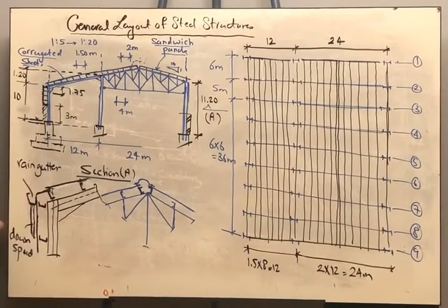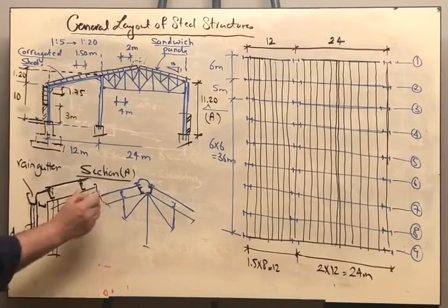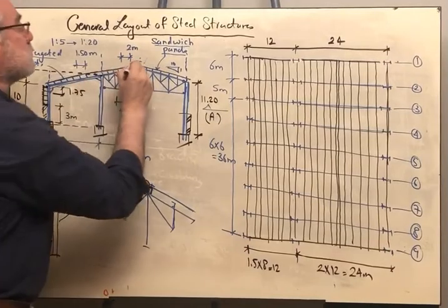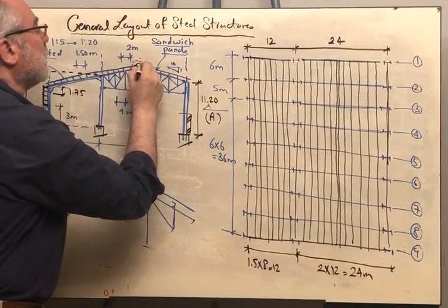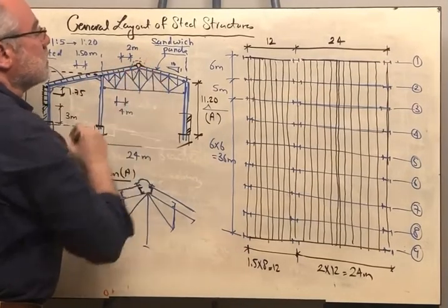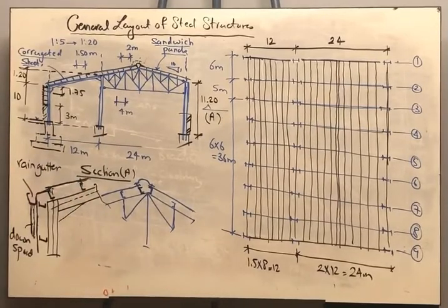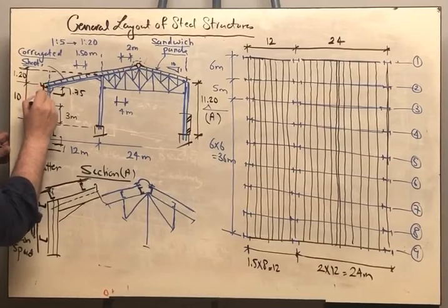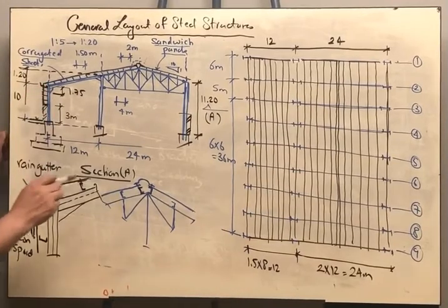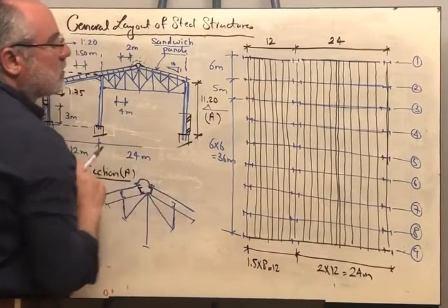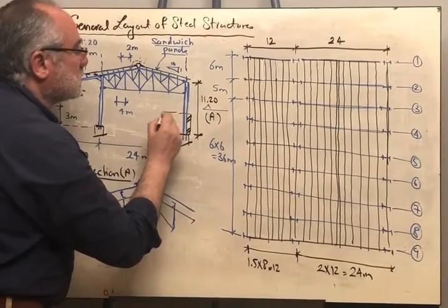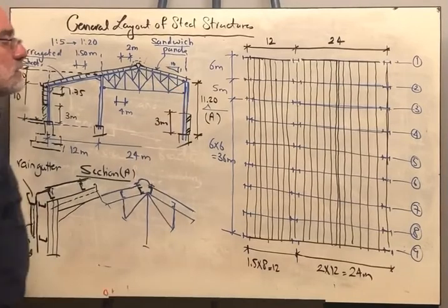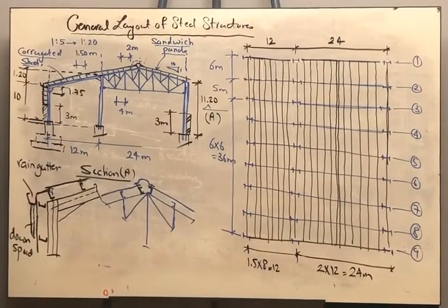This is how we close this corner, and we have seen how to close the apex. This is called the apex, that we should provide an accessory that will close this part like that. Again, here we are having the rain gutter like this, and if you look here, we are having this is 3 meters, and then remains for us this will be 8.2 meters.